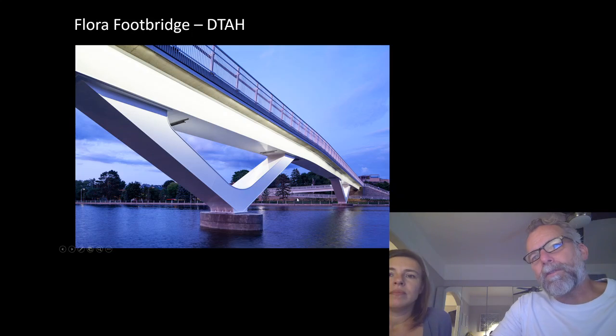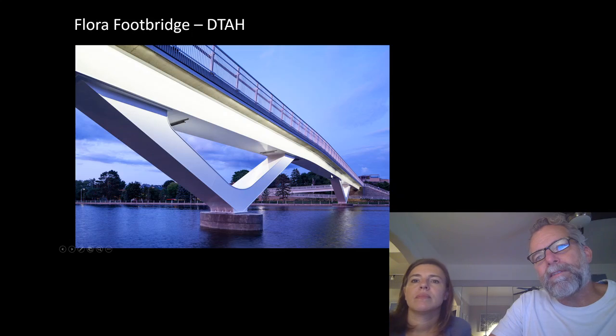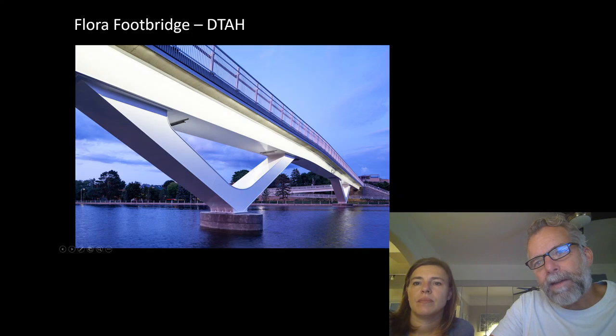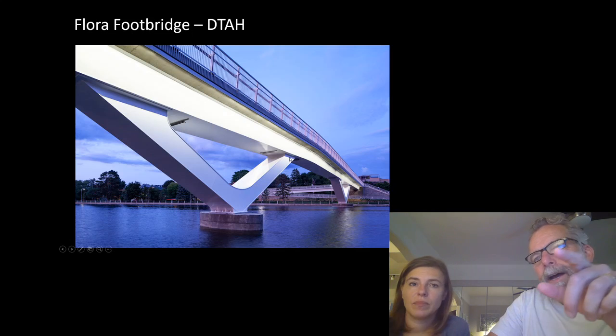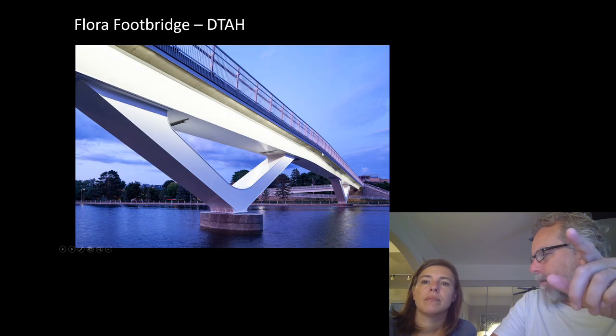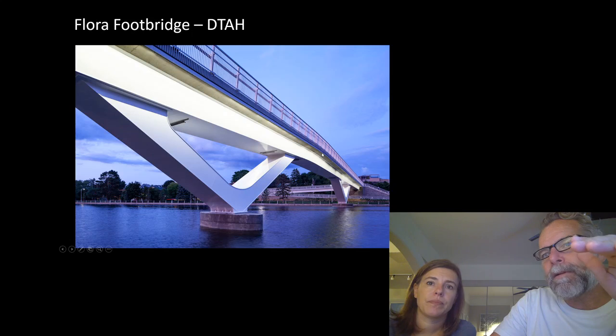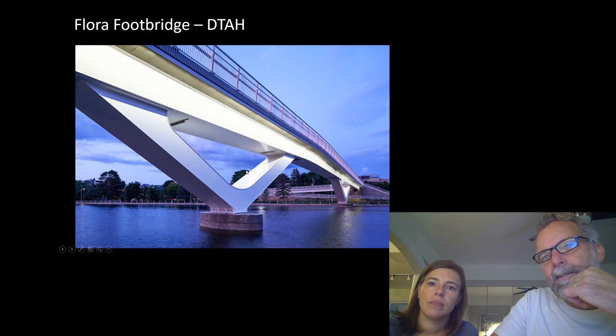So these are our box girders. So this would be a steel box girder. That's the bottom flange. A web on this side. There'd be a corresponding web on the other side. The top flange may be the concrete deck. That's a very common way to build highway bridges. It's very likely the way this was built. So the top flange of the box girder is the highway deck, and the columns are also box girders.